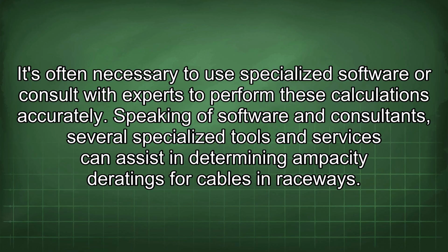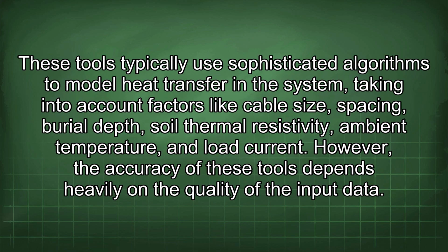Speaking of software and consultants, several specialized tools and services can assist in determining ampacity ratings for cables in raceways. These tools typically use sophisticated algorithms to model heat transfer in the system, taking into account factors like cable size, spacing, burial depth, soil thermal resistivity, ambient temperature, and load current.